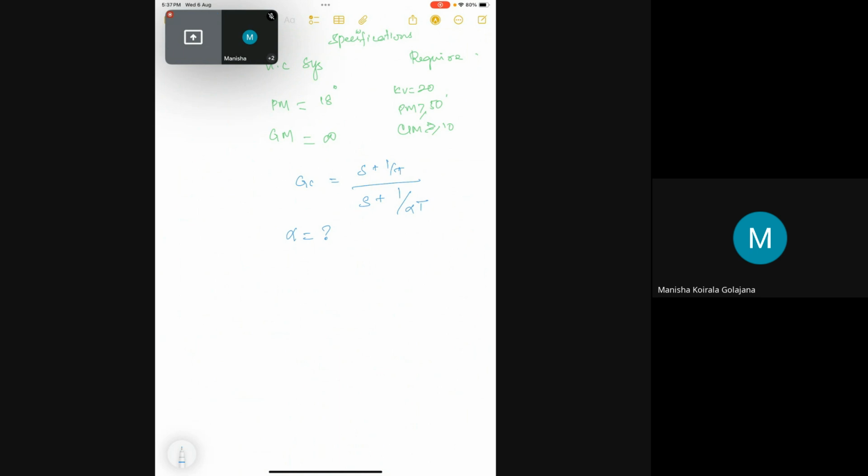Now, this phase margin of 18 degrees implies that the system is a little oscillatory. So satisfying the specification on steady state yields a poor transient response performance. When you try to do something for the steady state, if you achieve this phase margin, it will give you very bad transient responses since it is oscillatory. So the specification needs a phase margin rise of 50 minus 18, at least 35 degrees, right?